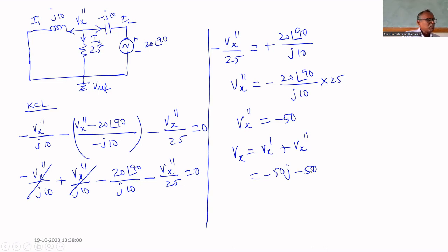Normally we won't mention any voltages in rectangular form. How is the voltage mentioned here in the voltage sources? 20 angle 0, 20 angle 90. Therefore, any voltage or current should be represented in polar form only, because the angle represents lagging or leading. Here you cannot find the lagging or leading. That's why convert this from rectangular form to polar form.